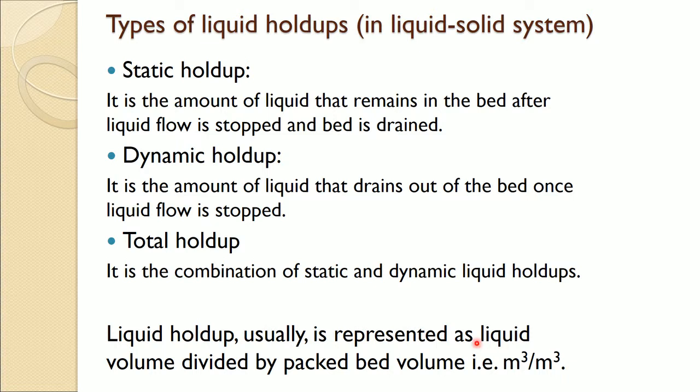It is usually presented in the form of meter cube per meter cube, that is, the liquid volume one collects divided by the packed bed volume is known as the liquid holdup. So, it is a non-dimensional quantity, on a meter cube per meter cube basis, in terms of fraction. These are two very important terms used in liquid flow through the packed bed.